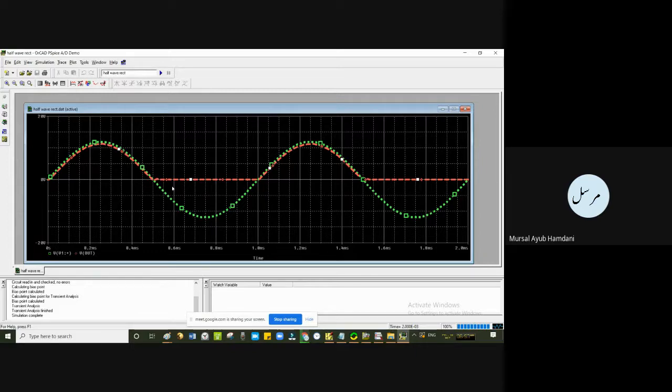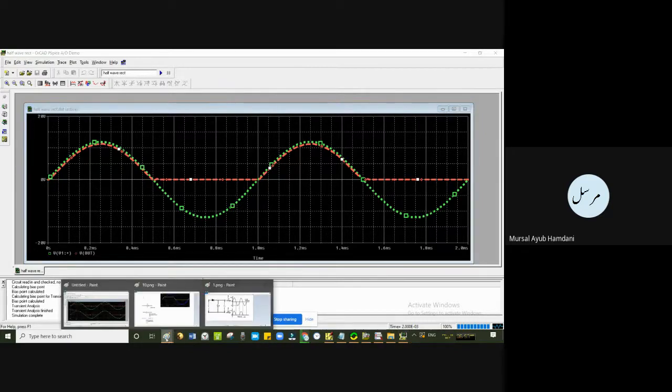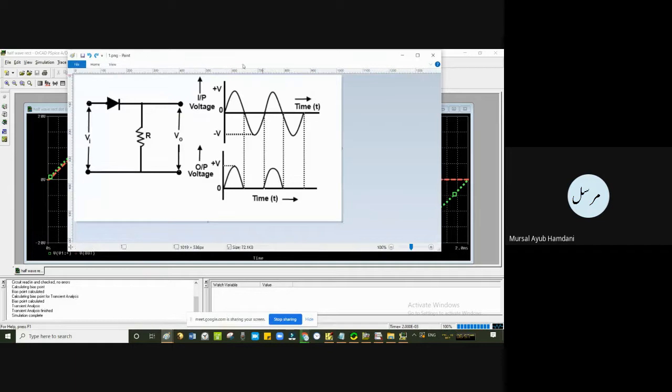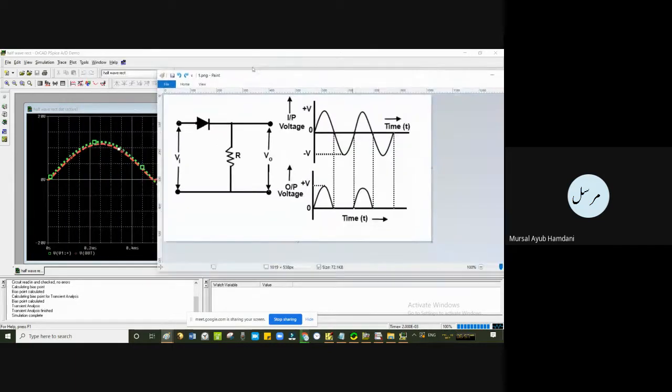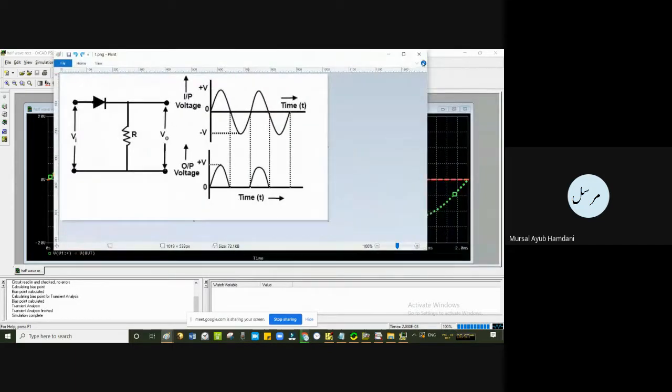It is a little lower than the value of the input. This is 0.7. I assumed a short circuit. However, you know that the knee voltage 0.7 volt is assumed, as you might have been told by sir in the lab class, so that is why it is a little bit lower. So this circuit is entirely coming about: half wave rectification.